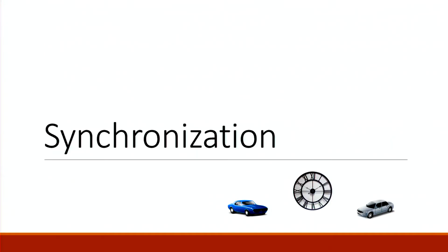Okay, let me skip to the last topic that I want to address today, which is synchronization in D2D. Synchronization, like I said, is important because you need to know the structure of the subframes, where they start and how you can interpret what's in there. Normally, when you are under coverage, you are synchronized to the eNode B. The eNode B gives you the synchronization.